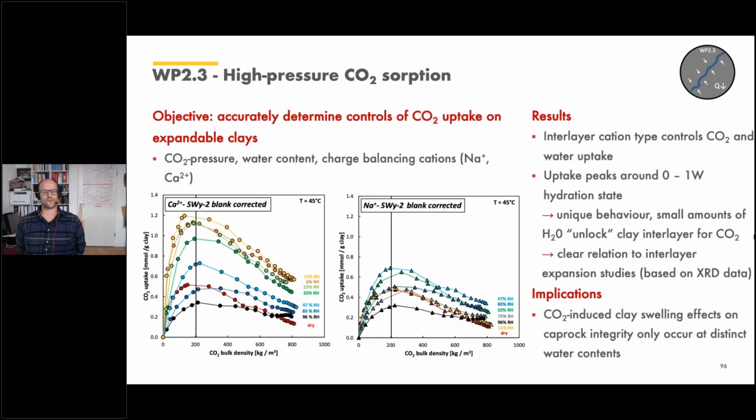What we first did is look at the CO2 uptake capacity of different smectites or swelling clays. We typically find different types in the deeper subsurface. Some might be calcium exchanged, so they have a slightly different chemistry, and some are sodium exchanged. We looked at the adsorption capacity of CO2 on these clay minerals as a function of relative humidity, going from very low relative humidity to full water saturation.